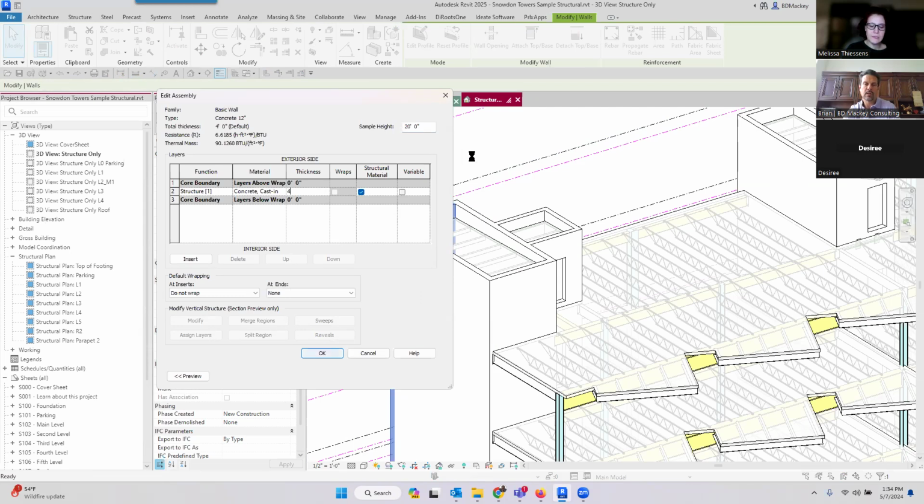Gonna break a whole lot of things here. Well, you can't transfer project standards for walls, right? The question said walls and materials. Sure you can. You can transfer project standards for system families. Walls are in there. Really? Crap, when did they add that? Probably like years ago.